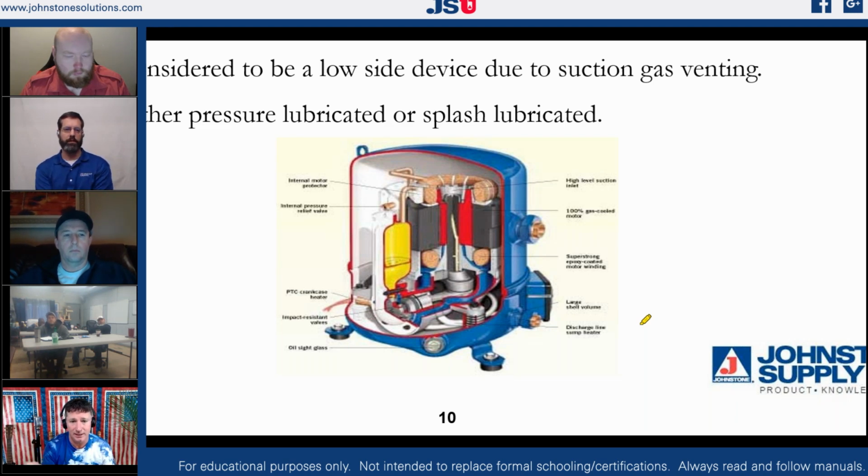This is another instance of why we cannot get liquid into our compressor. Even on this reciprocating, if I get liquid introduced into that, what happens if I get liquid refrigerant on the windings of my motor? Remember we were talking about in our motor class, yeah, we're going to destroy the insulation on our motor if we get liquid onto that insulation. If we get liquid into our bearing, we're going to have problems. If we get liquid into our oil in the bottom, we're going to get a problem with lubrication on our lower bearing and on our crank, right? So we cannot get that liquid into our vapor pump.